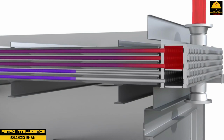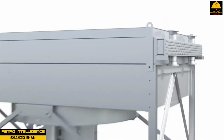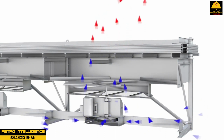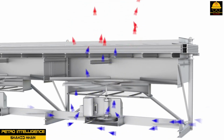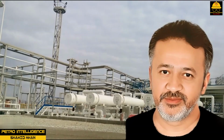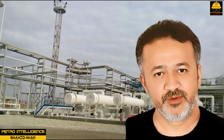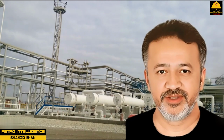Aluminum blades are designed to operate in temperatures up to 300 degrees Fahrenheit or 148.88 degrees Celsius, whereas plastic blades are limited to air temperatures between 160 degrees Fahrenheit and 180 degrees Fahrenheit or 71.11 degrees Celsius, 82.22 degrees Celsius. Air-cooled heat exchangers can be found in service on air compressors, in recirculation systems, and in condensing operations. This type of heat transfer device provides a 40 degrees Fahrenheit or 4.44 degrees Celsius temperature differential between the ambient air and the exiting process fluid.